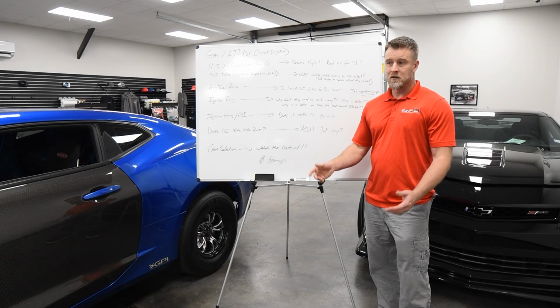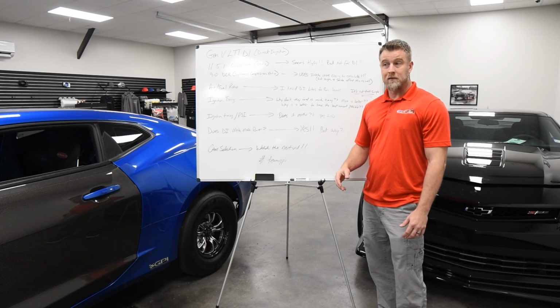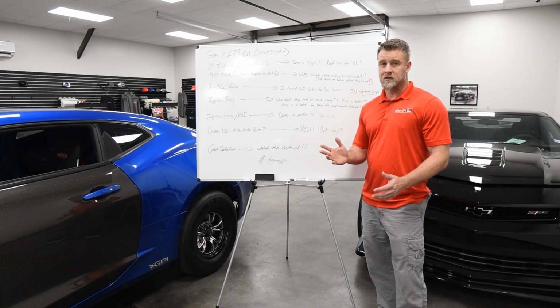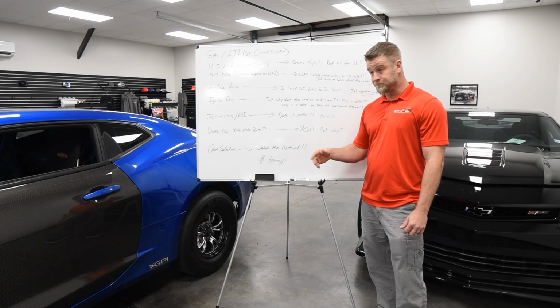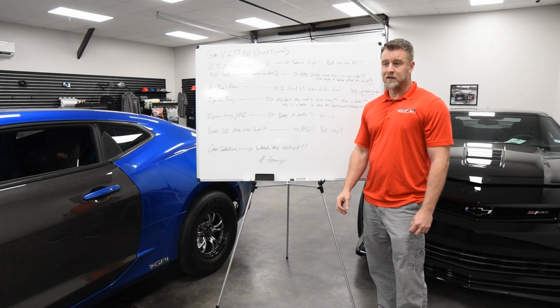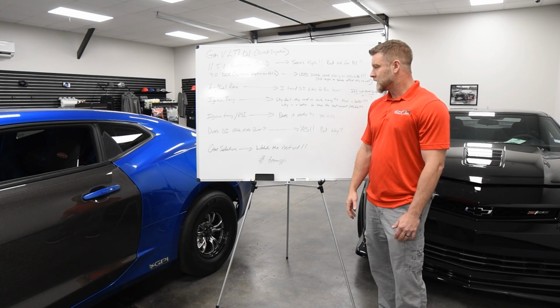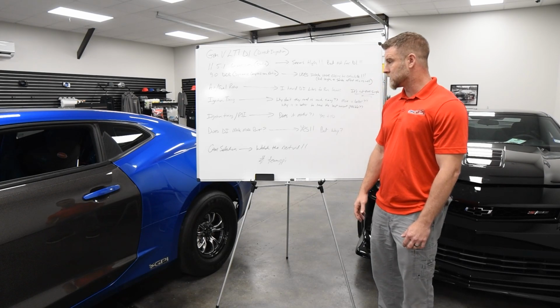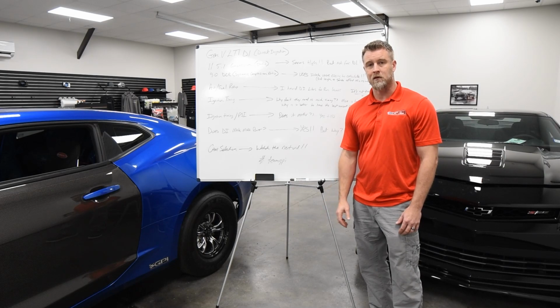The problem is, beyond the naturally aspirated stuff, it's very hard to make big power on direct injection alone. So you start having to put port injection on or methanol injection, and at that point, you have to start treating it a little bit more like a port injected motor. So it's good when you can utilize 100% DI. It's absolutely worth more power.